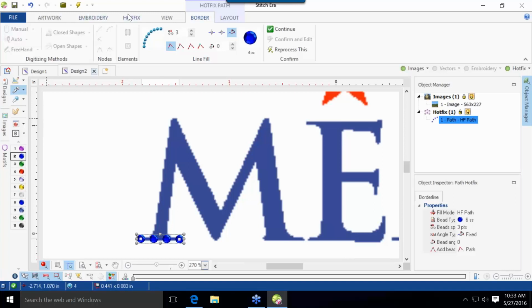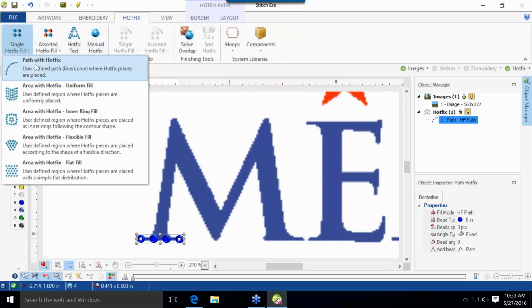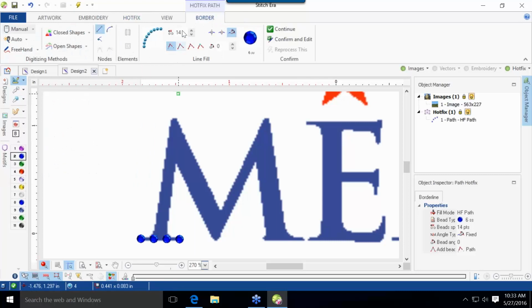And then we'll go back into manual. I'll set bead spacing to 3, and I'll start from here with the small stones, right to here. I'll go to my SS10 stones, set my bead spacing to 4, and I'll start from here, come straight down here.